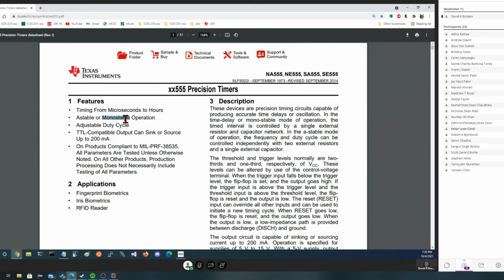A second one is called astable, which is the one we'll probably be using mostly, which says that both states that it can assume will want to get back to the other state. And then finally, there's one called bistable, which is very stable in both states. We'll talk about that next class using a different type of chip.